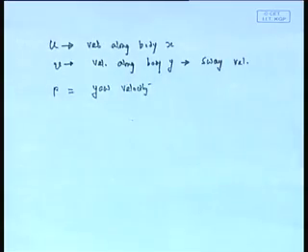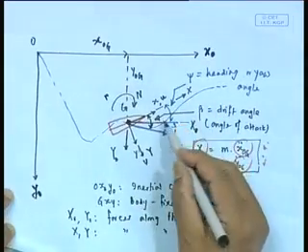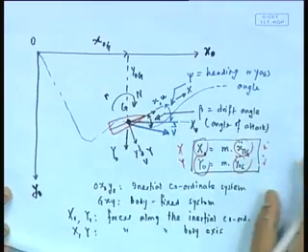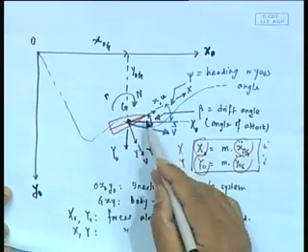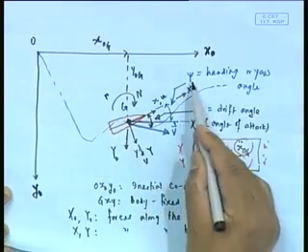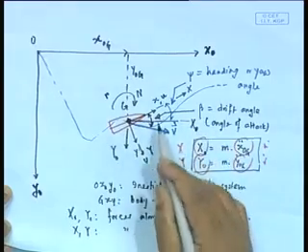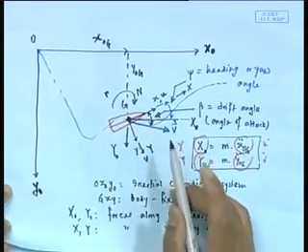Actually, you will see from here that r is psi dot. Remember that when you are doing dot, it is always the rate of change of heading. Remember psi dot, not drift dot. Okay, it is not beta dot.